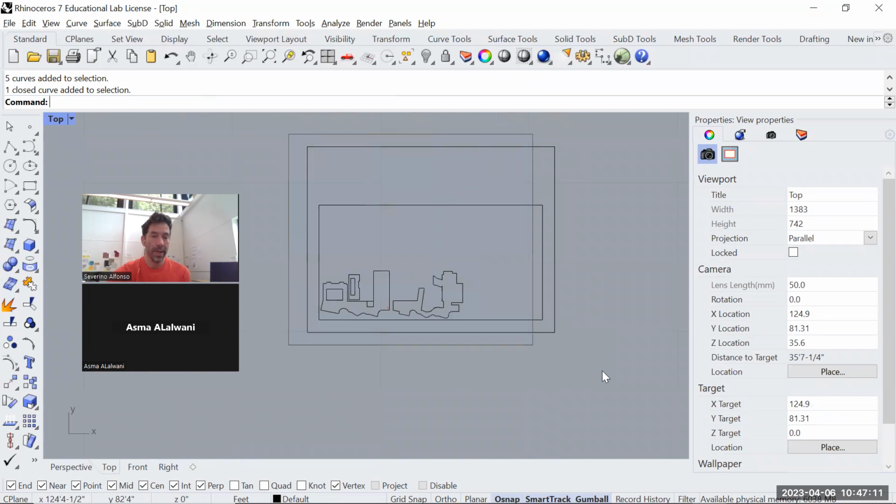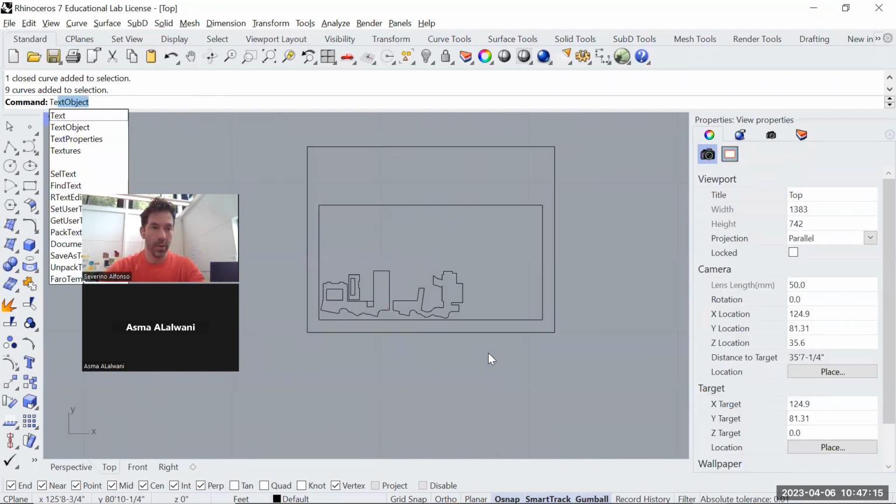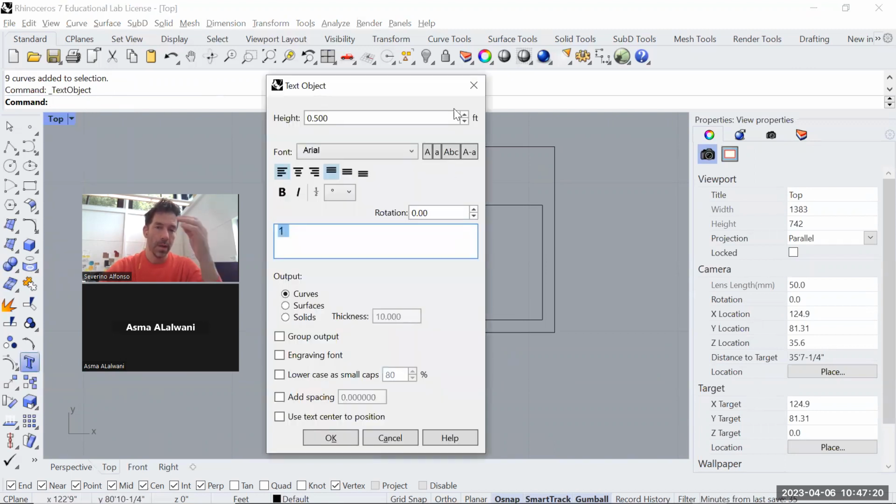This is the file you send them. And what I recommend is that you always add text, whether it's in AutoCAD or in Rhino. I would recommend you write down comments to the side of your drawings and say, red is scoring, please do this.